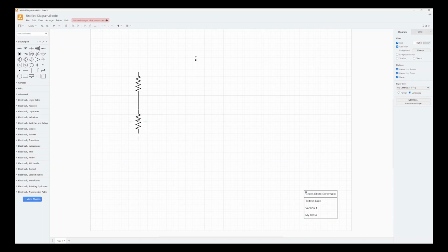So let's think a little bit more about this diagram. Let's say that I want an op amp. So click on that, bring that in. And let's say that I need to do a connection between this op amp and this set of resistors here. So I'm going to go here. This is called a waypoint. And it appears over here. So I'm going to drag it onto those resistors. See, there's that arrow again. This is going to let me connect to some place.